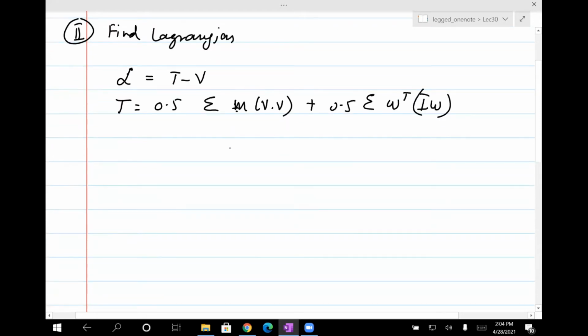Now, what I did was, in this case, the body is one rigid body, the legs are two rigid bodies each. So I call this the thigh. I call this the calf. Sorry, this is the thigh, calf, right? And then this is the body. So there are 5 rigid bodies. Okay, and I put some mass, and then the velocities will be the velocities of the center of mass, VB. So that can be found because you know the position vector and you can differentiate.